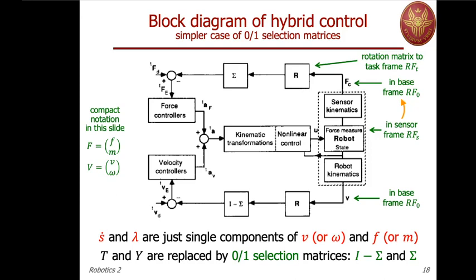And those are the velocities that are feasible, so those that are compliant, or better said, that are not barred by the presence of the environment, so the free motion directions. Again, we compare with the reference value, we generate an error, we have the velocity controller, for instance, a PD version of this, but this can include also an integral term and be the position control with a PD in that case.